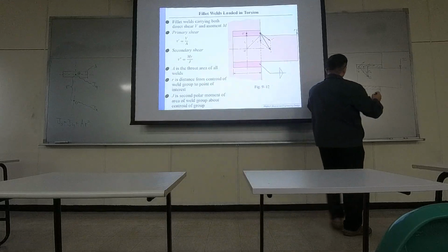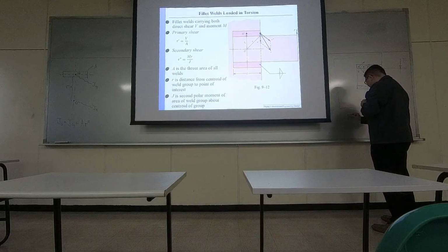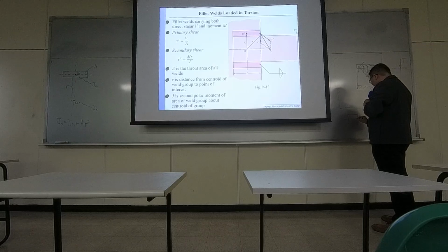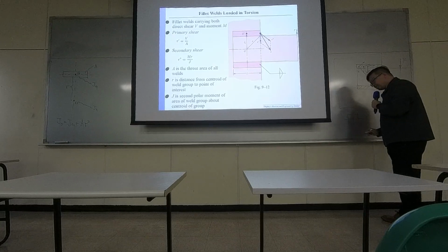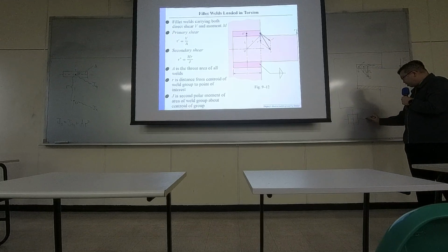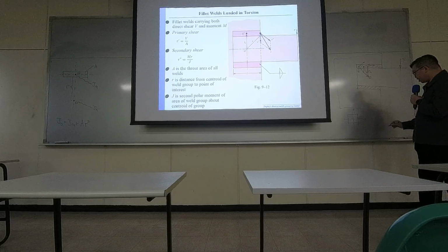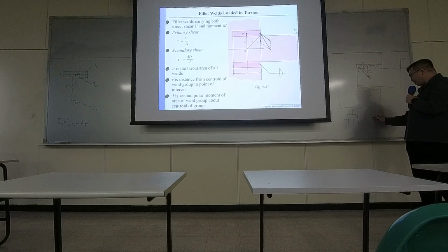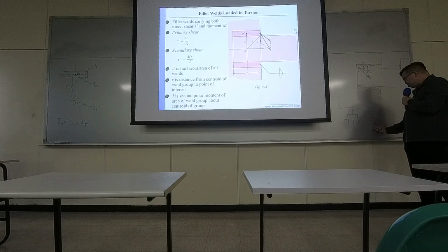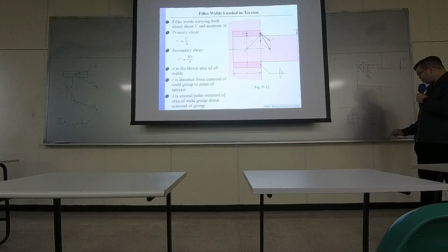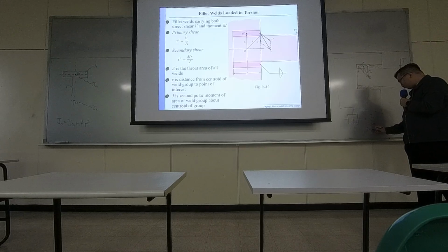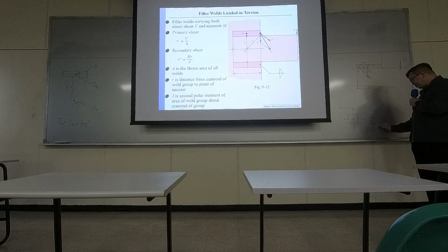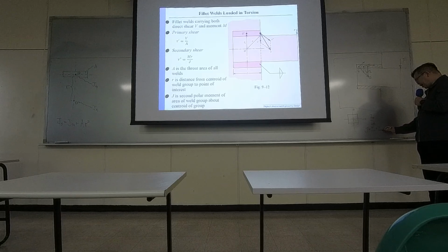So usually when you take a look at the textbook, if this is an x coordinate and y coordinate, usually the book tells you Ixx, Iyy, and also sometimes people use Izz, or sometimes people just call it J. And J can be computed by Ixx plus Iyy.